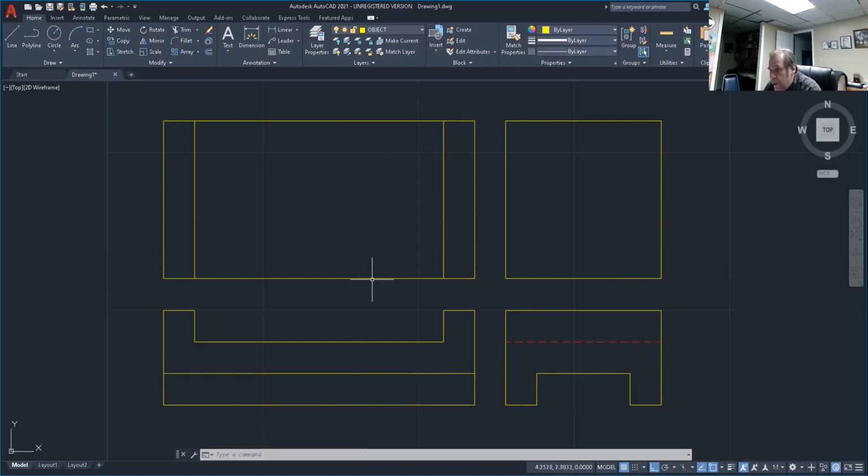Now, this line here is not visible as you look at from the front view. It's back in the middle of here. So this becomes a hidden line right here. So let's click on the line and we'll go up here, hit the down arrow key and hit hidden right there. Okay, and then hit escape. So our front view is finished.